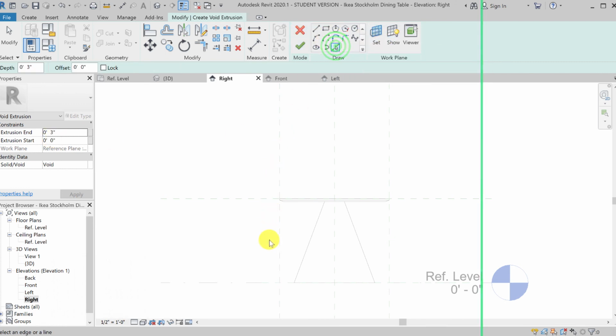I'm using pick line. Again, I want to make sure that I pick the base reference plane and not reference level. So I'm going to tap until I get base reference plane and lock to it. For the remaining, I'm going to enter an offset value, 1.5 inch. Same as the opposite. And 4.5 inches from the bottom of the table. And then TR for trim extent to clean up the profile.